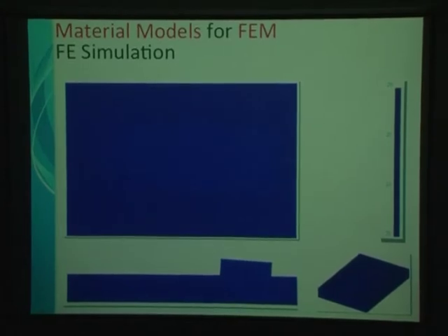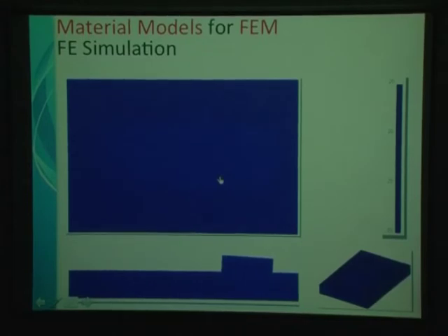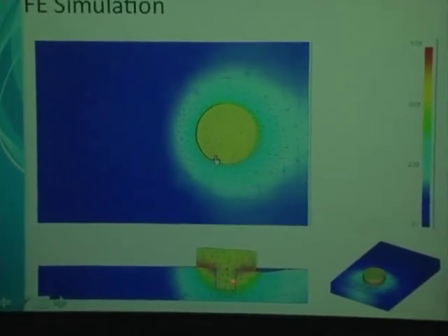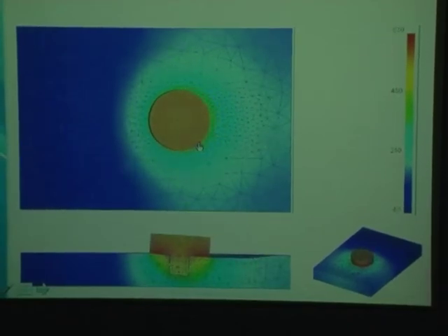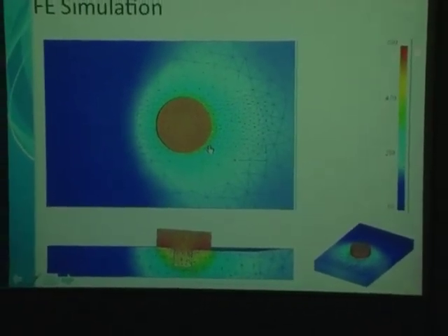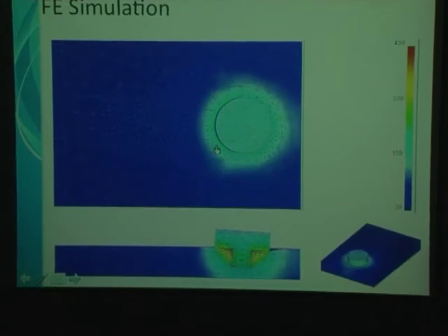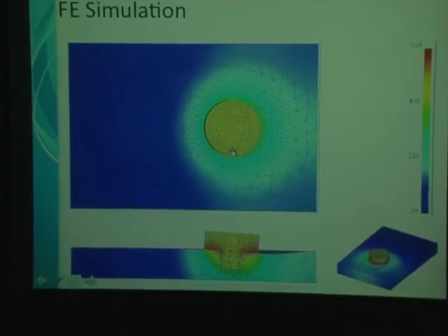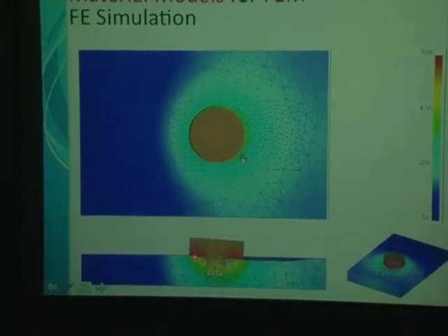Once we're happy with this, let me just show you basically what the run would be like. So this is a typical DEFORM run. Again, this is the tool, top view, side view, and it's moving in that direction. And it's showing you, in this case, how the temperature is going. It's going up to, what was the final value? 600. What's the melt for magnesium? It melts at 660. So again, if you look at this area, right underneath the shoulder, it's really close. So I see 600.